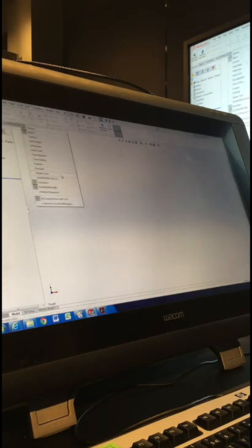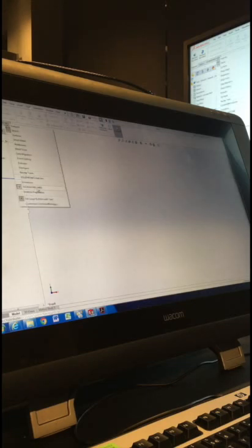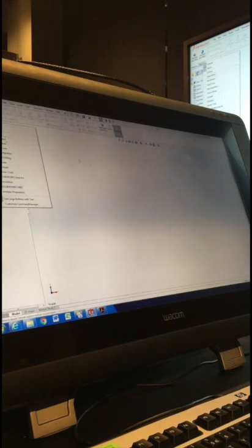So that's the Command Manager. Now there are tabs here, and we can turn them on and off. You can right click on the tab and the ones with the tick are currently on. The only ones we really need are features and sketch. The rest of them you can turn off. Most of those, evaluate, simulation, analysis, are a lot more advanced, a lot more engineering based. We're not going to touch those this semester. There are some others like surfacing and sheet metal we'll look at later on, not today though, sometime in the next couple of weeks.